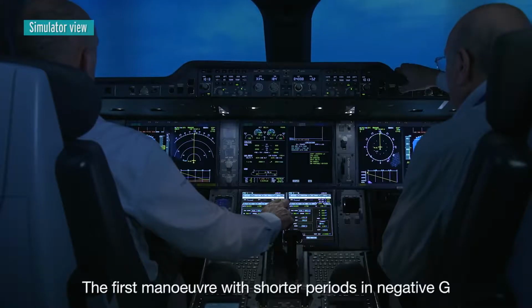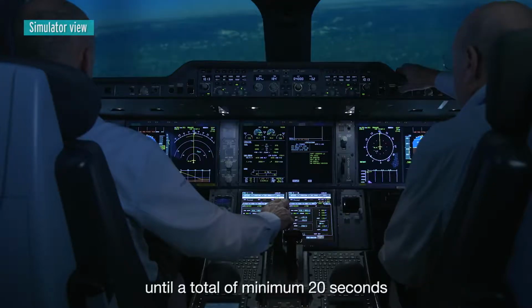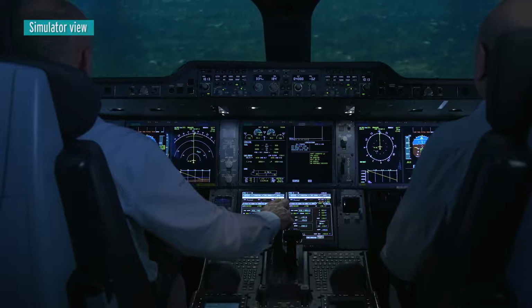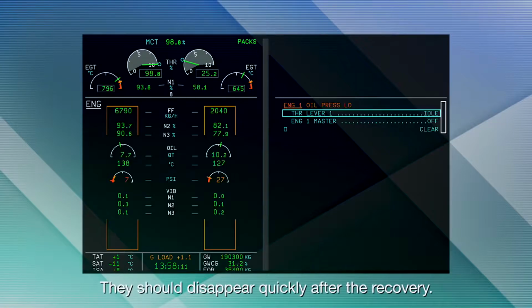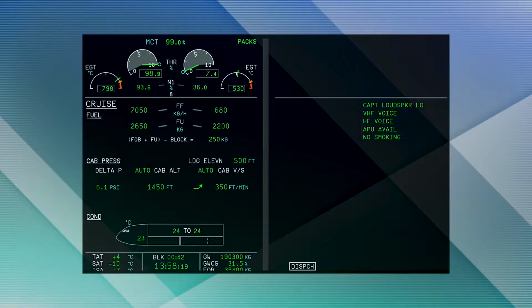The first maneuver with shorter periods in negative G is repeated several times until a total of minimum 20 seconds at less than 0 G during the flight has been achieved. There may be various warnings during these maneuvers. They should disappear quickly after the recovery. All systems are checked carefully after each sequence, with a load factor at less than 0 G.